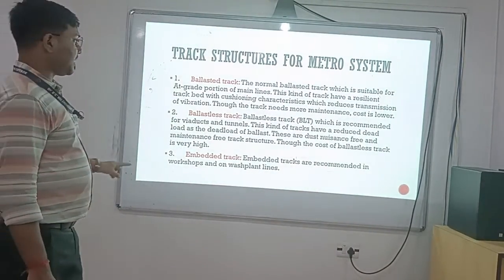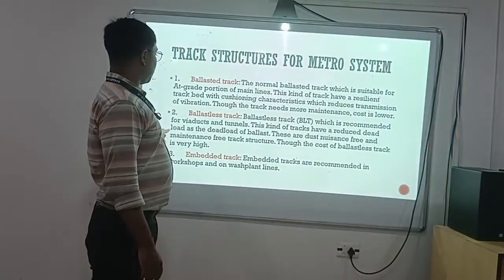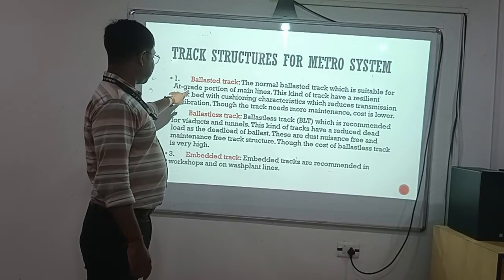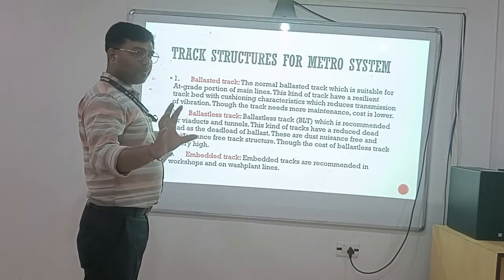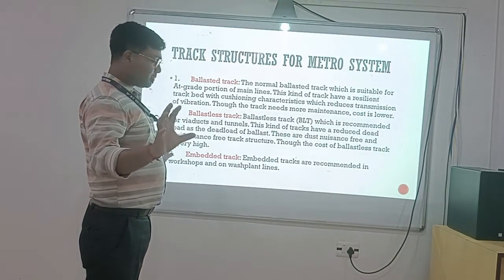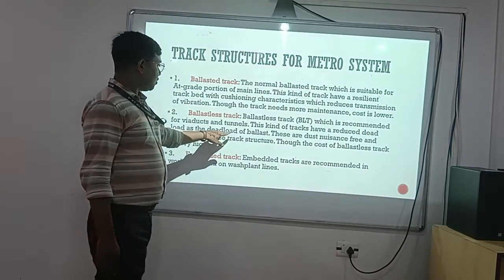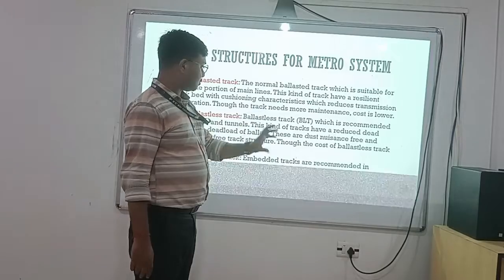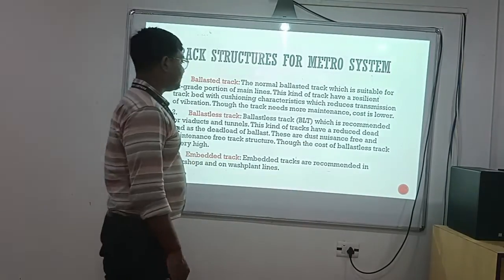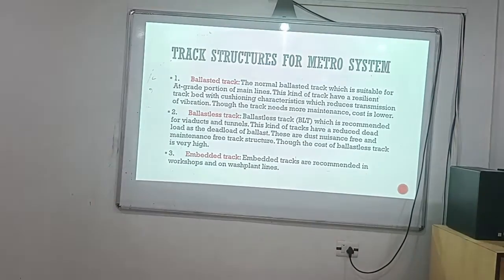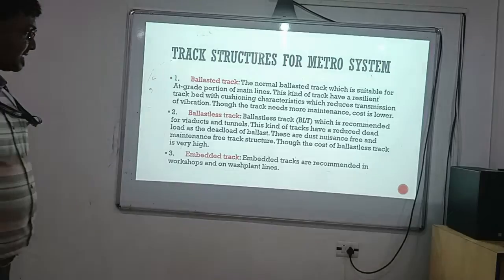These kinds of tracks have a reduced dead load. Why? Because the ballasts are not present there, so the load of the ballast is not present. That's why the dead load is lesser. Now these are nuisance-free and maintenance-free track structures.